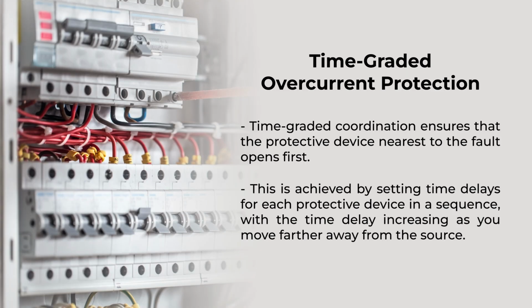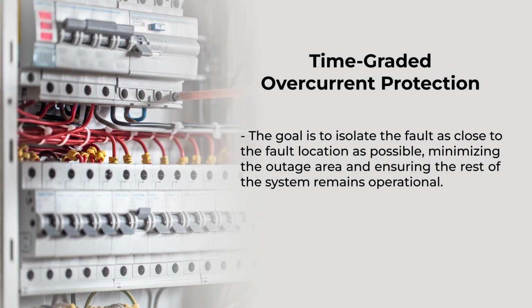This is achieved by setting a time delay for each protective device in a sequence, with the time delay increasing as we move further away from the source toward the load. The goal is to isolate the fault as close to the fault location as possible, minimizing the outage area and ensuring the rest of the system remains operational.